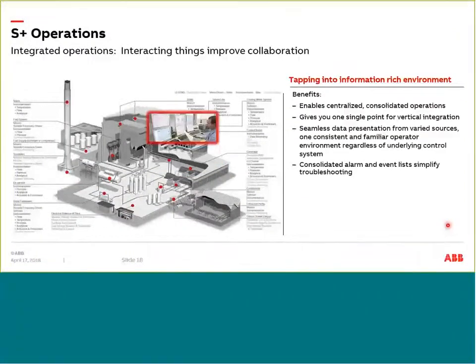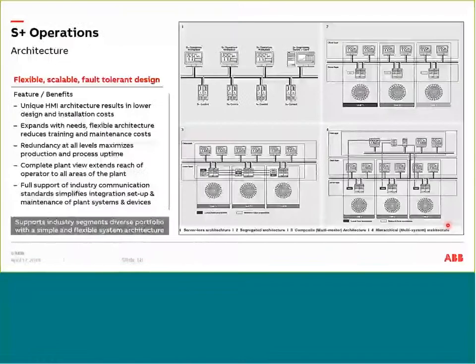And what this does is it removes the islands of control. And when you remove the islands of control, you have a centralized location where the operator can make decisions. Now you have consolidated alarm and event lists. So imagine that instead of having disparate systems where you have to see what was the event that triggered in my system A and did that cause an issue with my system 2. Instead of all that, when you have it consolidated in a central location, it's easier to troubleshoot any issue that might have tripped the plant or issues that you see out there.